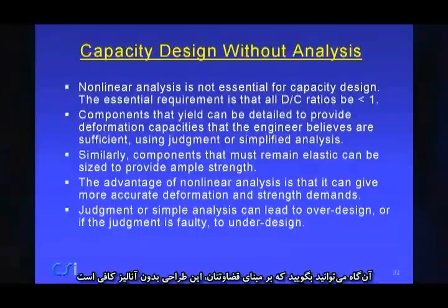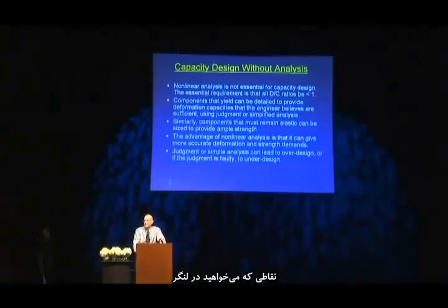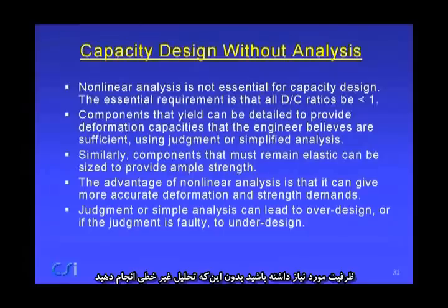You might say that based on my judgment, this is sufficient even without analysis. Similarly, further up the structure, where you want to remain elastic in bending and elastic in shear, maybe you can make some pretty good estimates of what the capacities need to be without running a nonlinear analysis. Perhaps you could run some linear analysis or use some judgment.